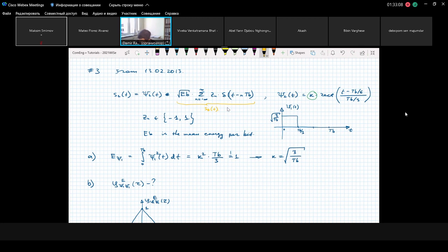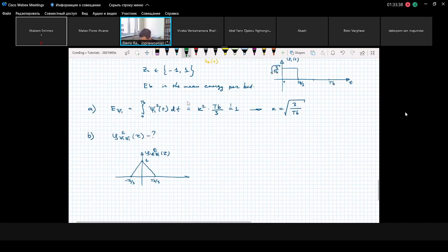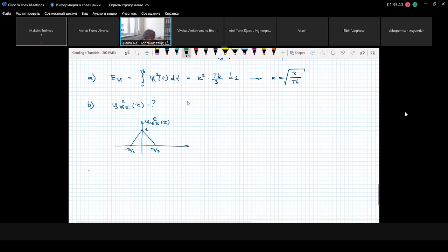And of course, as we did before, in order to do this, first we calculate the discrete autocorrelation function for the sequence, and then we normalize it by the duration of one symbol, which is T_b, and it helps us to find the resulting autocorrelation function for this discrete sequence. And of course, we also should multiply by E_b. So let's do this in part C.